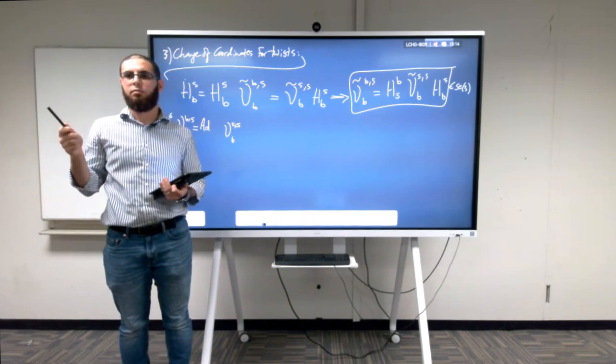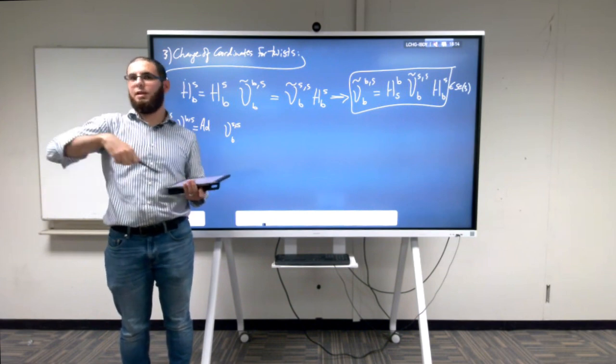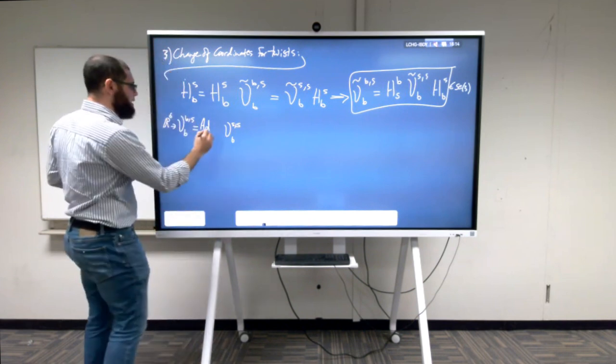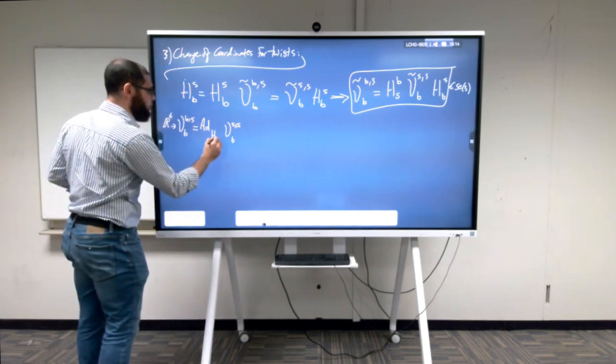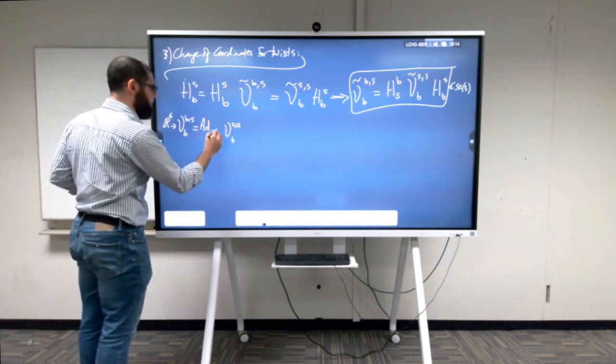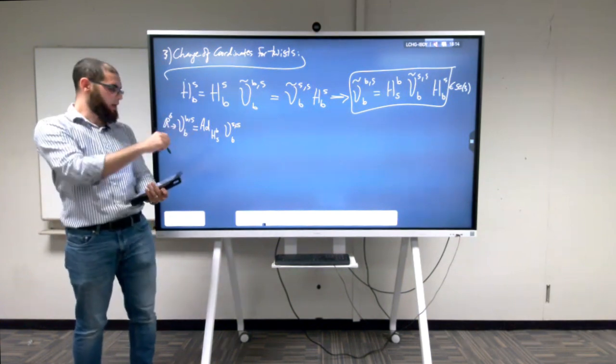Why only one? Because the same information, right? So what's in B with respect to S is the same as what's S with respect to B, just represented differently. So this is a function of the homogeneous transformation that would take you from B with respect to S. We're going to write it from S with respect to B. Why did we choose to do it like that?